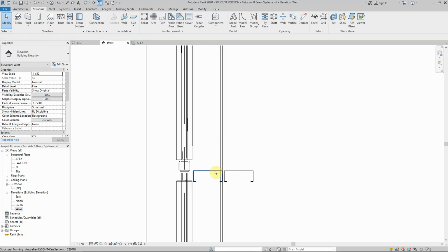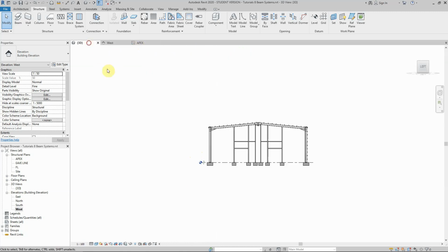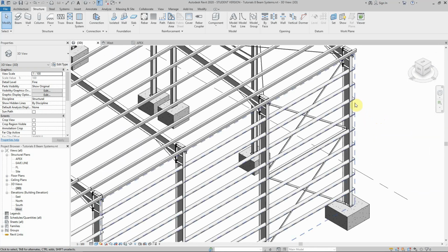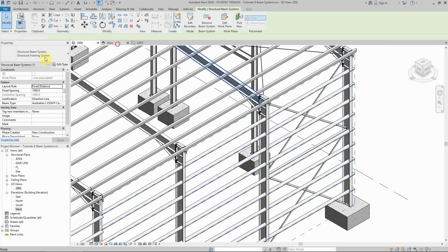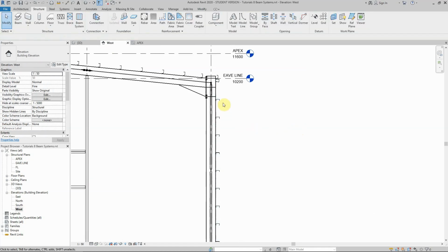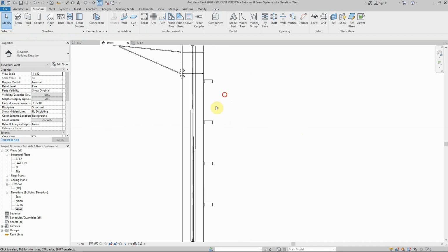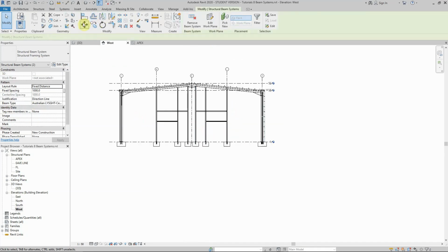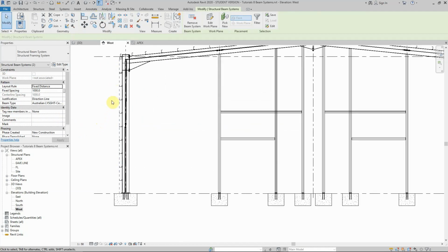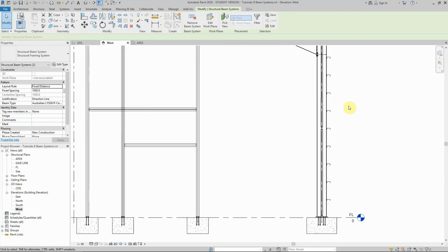Tab. Let's look at it in 3D so we can select that. This is the one still sitting within the columns. Selecting that, going back to the west elevation and move it 213mm to the outside. Okay, I don't see an issue for copying, for mirroring those to the other side. We can just simply mirror. That shouldn't create an issue about the rotation. All what we've got now, simply just to rotate those downward to be similar to those girts here.